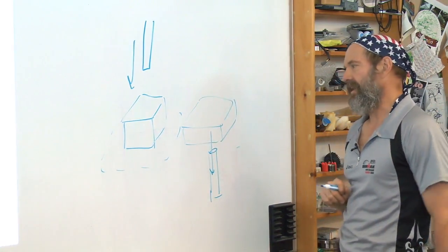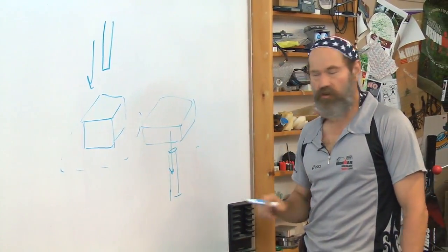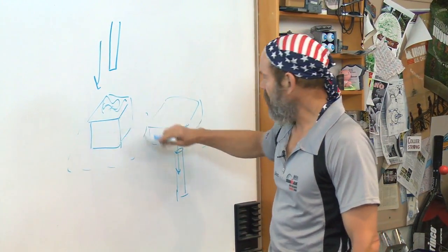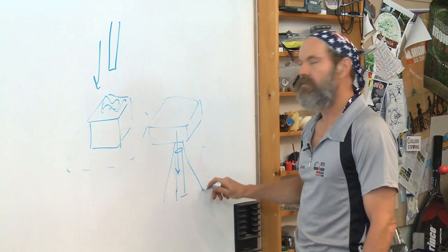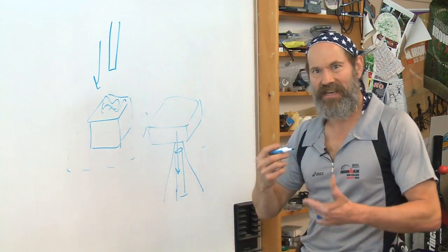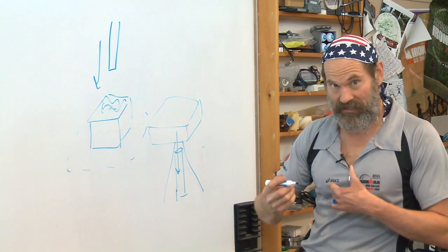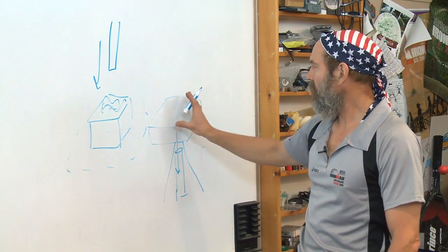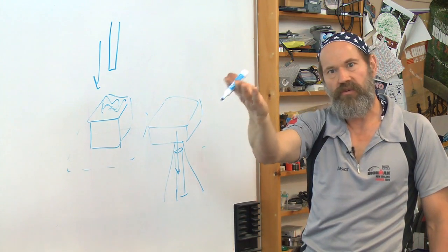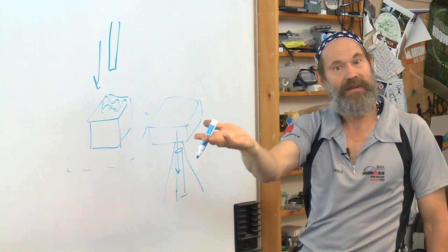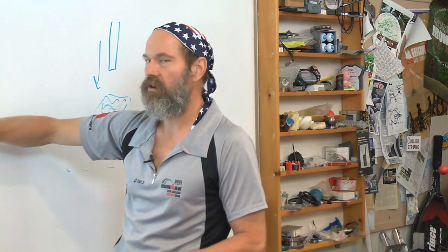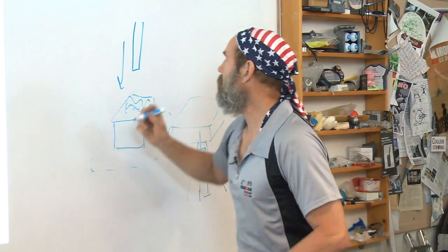Why would you ever want to do that? Well, anybody who's drilled knows that when you start drilling, you get all kinds of chips in here. And if I do it upside down, the chips will fall. So yeah, but the part will fall. So this idea, and you'll also see, is called persistent questioning. Well, why don't I fixture the part here, and when I'm ready to drill, I flip it over? Using reversal again. Very, very powerful technique.